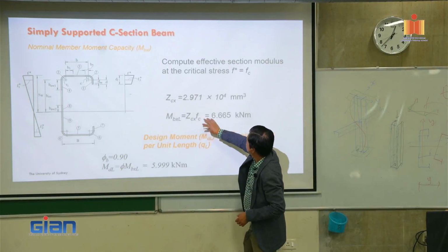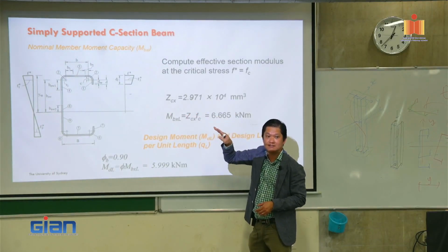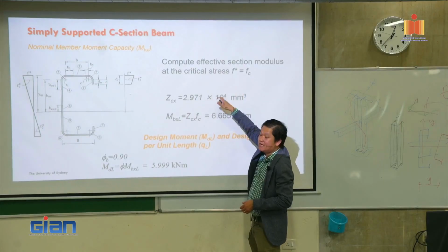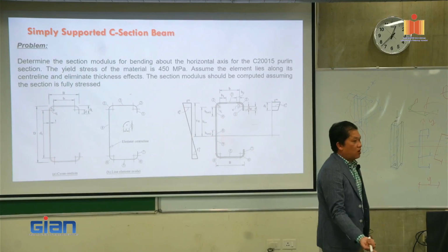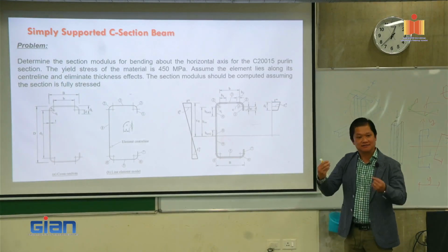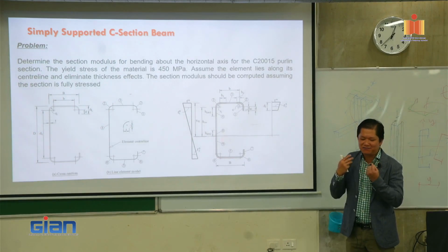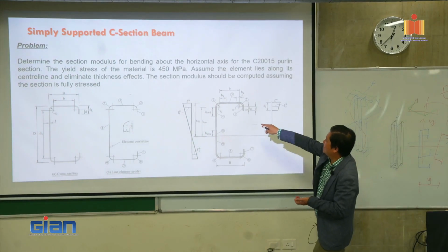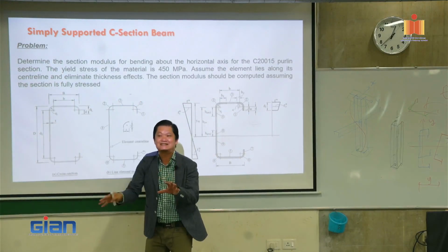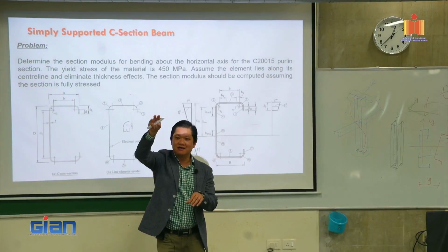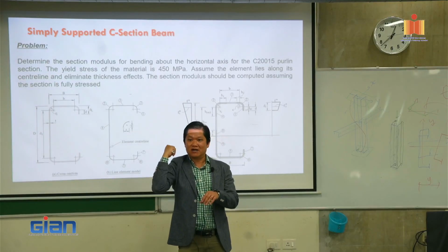So now this is where we calculate the effective section modulus at this stress, okay? Next, I will walk you through how to calculate the section modulus of the effective area of the beam, but with the stress here equivalent to the maximum F star. So it's exactly the same procedure. You just replace F star equal to 450 with whatever we calculate here, Fc.